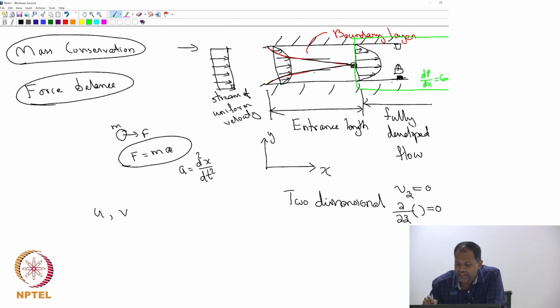So, you have applied pressure on this side, and then the fluid in between experiences that pressure and is going to go there. So, this is where pressure is going to be larger, inlet pressure is going to be larger than the outlet pressure, and it is just going to vary linearly, in fact, because dp/dx is a constant. That means p is a linear function of x, p will just change linearly with x. Clear?